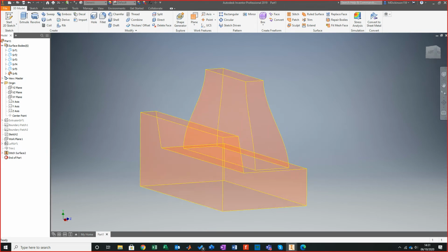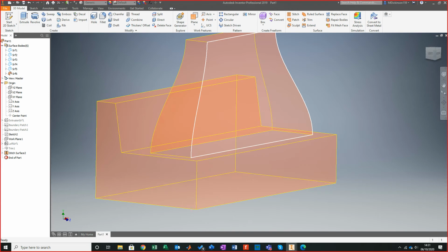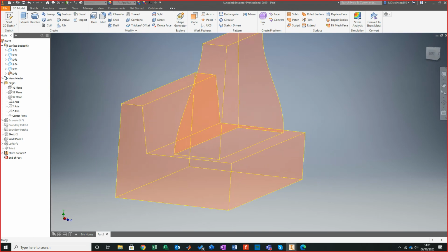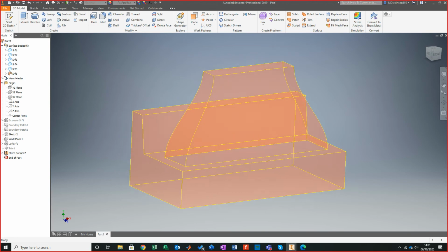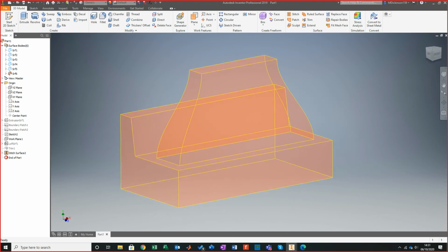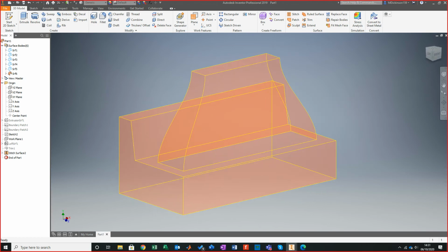But again, if this wasn't closed, if I didn't trim out the surfaces from the inside, if it wasn't basically an empty box, this would not work. This would not knit together as a solid. Part of your assignment, one of the key things I'll be checking, is that you were planning for this. If you don't plan for it, it can lead to failure. Why spend all that time generating a surface model that clearly does not work?